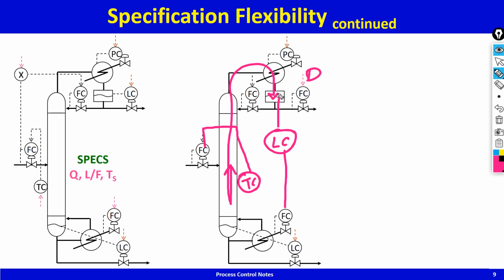If the pressure controller is on manual, then the level control will not happen because you are not condensing more or less, because you are not adjusting the cooling duty of the condenser. Nevertheless, level control will be achieved as long as the pressure controller is always on automatic. So this is the way this works with a nested loop. Level controller is nested with the pressure controller,